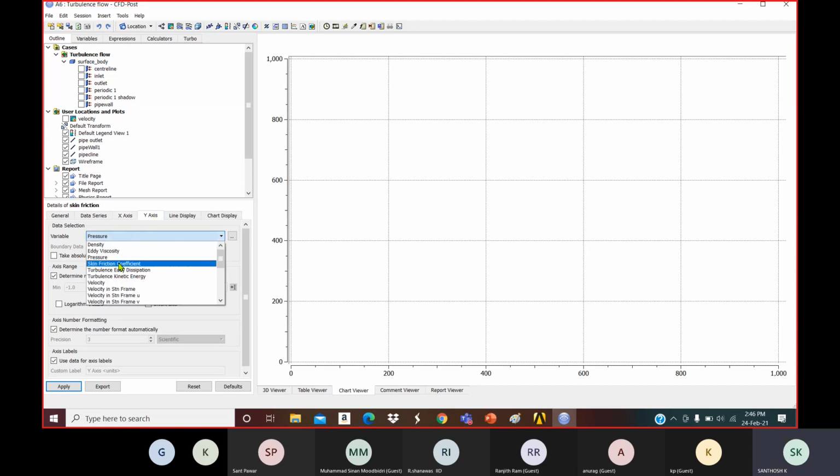No, see, suppose you are not updating there. What we did is I went to File, Other Quantities, right? If you're not selecting there, the skin friction will not be displayed here. So definitely go to File, Other Quantities, and select that. When you select it in Fluent, only then will it be visible here. If it's not visible, again this will be a problem. Okay, click on that. So try to apply that.